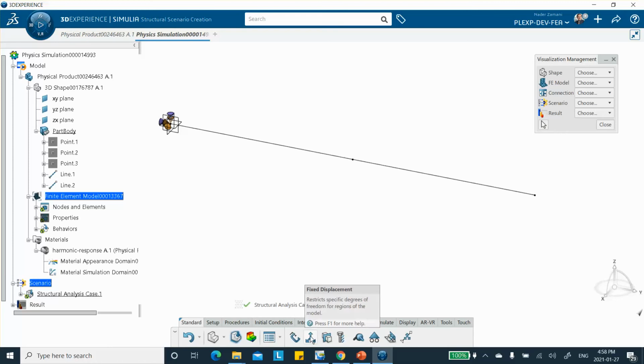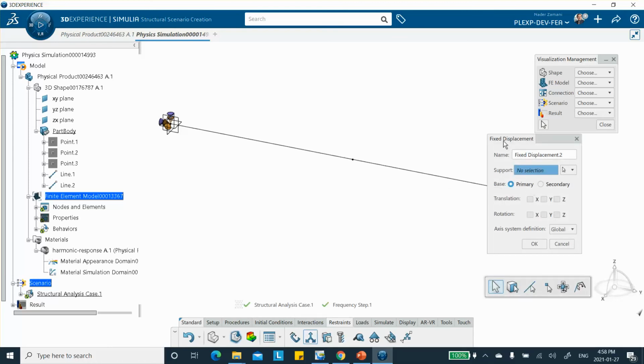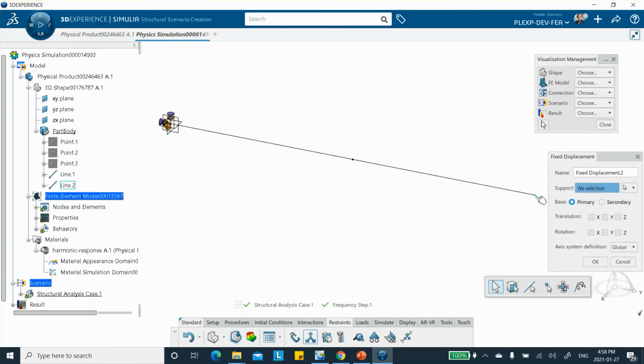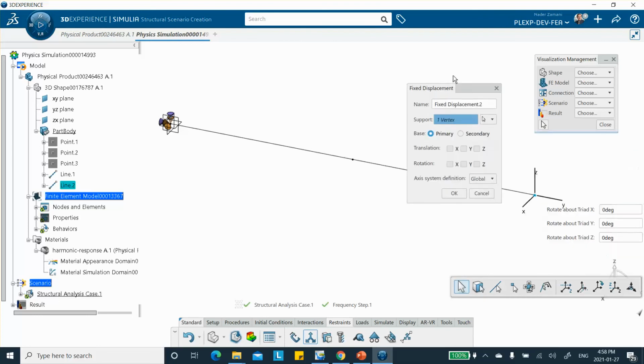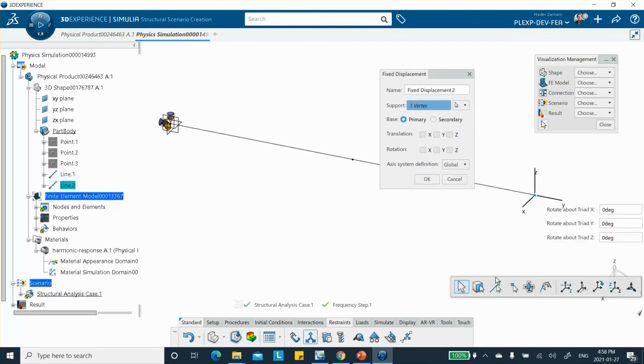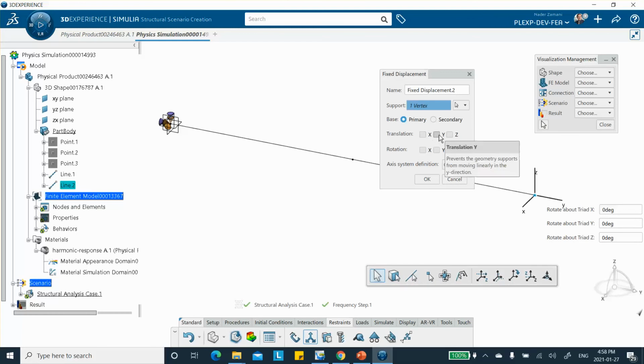And the other one on the other side, this was on a roller, so it can move in the direction, let's see now, direction Y. It can move in the direction Y, so X and Z are fixed, but again, it can rotate about the X-axis, but not about Y and Z. So that's what a simple support is.